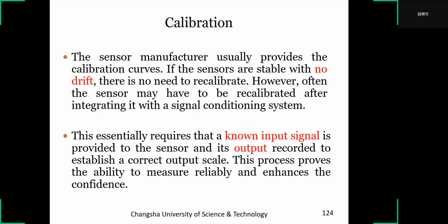This essentially requires that a known input signal is provided to the sensor and its output recorded to establish a correct output scale. This process proves the ability to measure reliably and enhances the confidence.